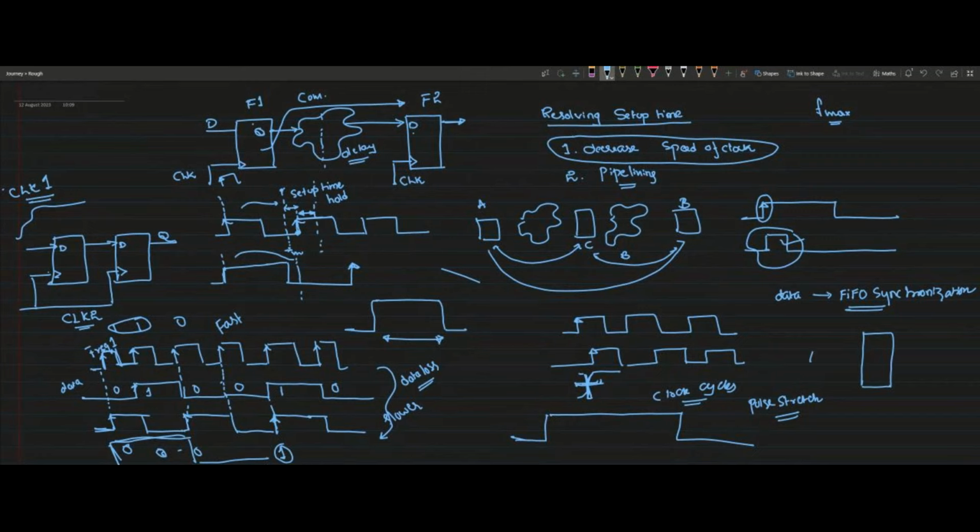We will write the data at the write clock and get the data at the read clock. So it can be an asynchronous FIFO. This is for data transmission, but if it is signal transmission, we go with pulse detection or pulse stretching.